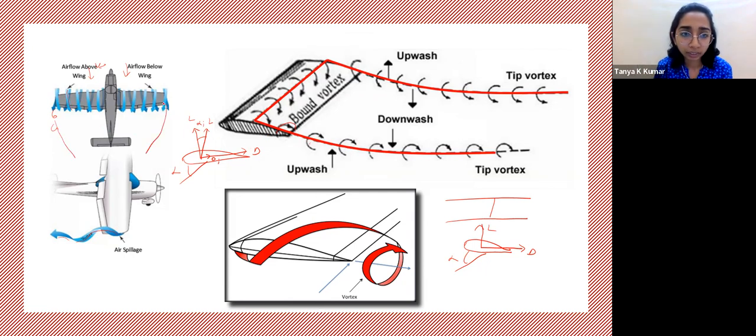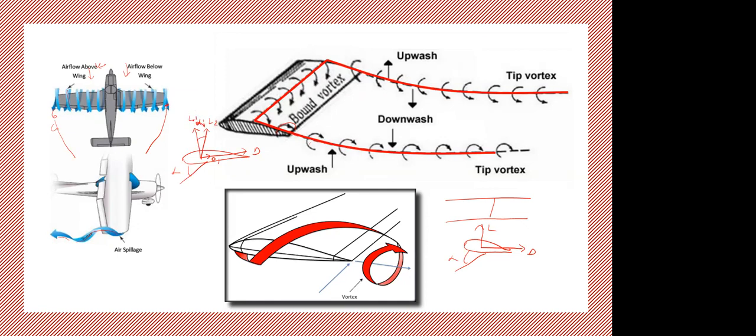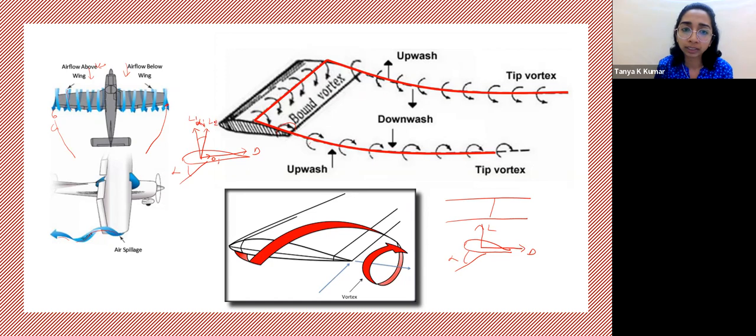Because of this, when the flow changes here, at this point, it's not the same uniform pattern that was there throughout the other cross sections of the wing. The flow changes, and there is a different angle of attack. So the effective angle of attack will also include this induced angle of attack term now. Because your lift is tilted. Initially, this was lift 1, this is lift 2. It was initially perpendicular to drag, but now,